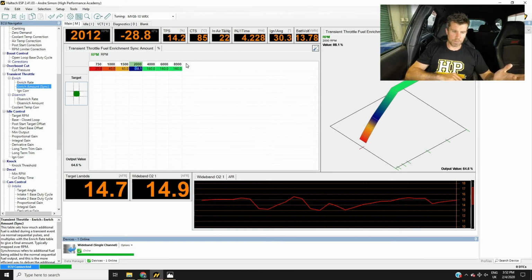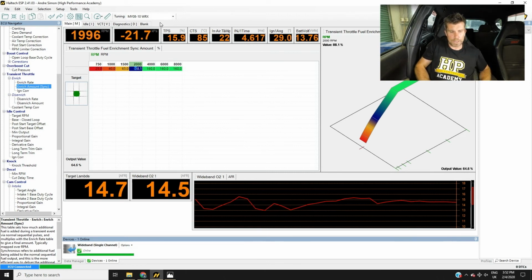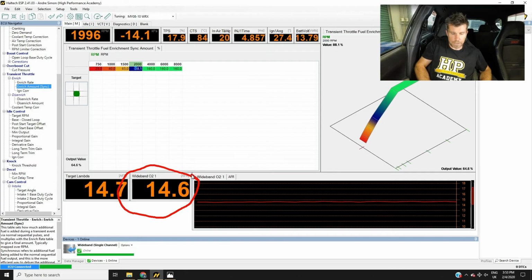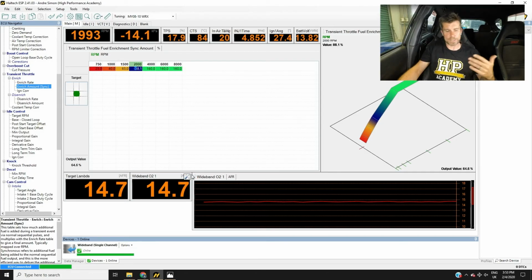And what I'm going to do is come up to a point where, let's say, we try and get us to about minus 15 kPa. So light load here, and what we want to do is initially just wait until our engine has stabilized, reached equilibrium. We can see that our measured air fuel ratio here is sitting between 14.6, 14.7 to 1. We've obviously got pretty good control over that right now, and that's being shown also in our time graph to the right with a nice flat line.